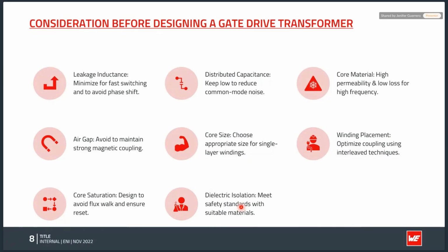So we also need to think about what we can do inside this small gate transformer. Also, with this kind of isolation, we need to think about how we're going to test or comply with partial discharge. So in summary, transformer design isn't just about turns or voltage; everything you think about in layout and material decisions will influence the final performance.